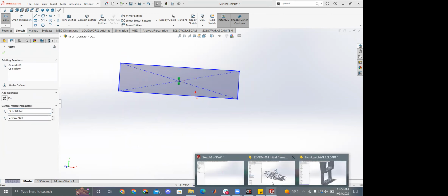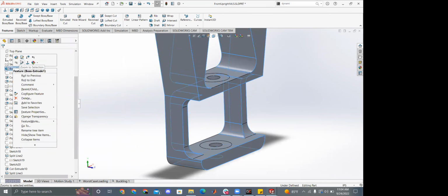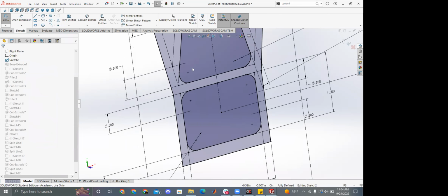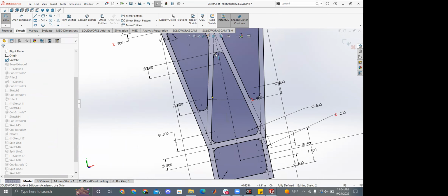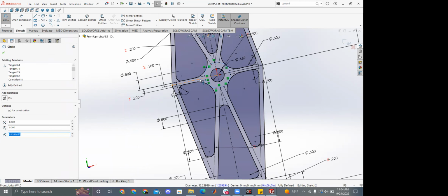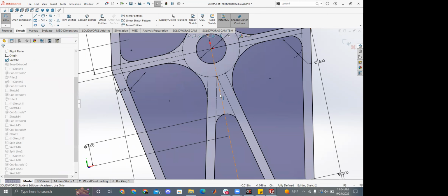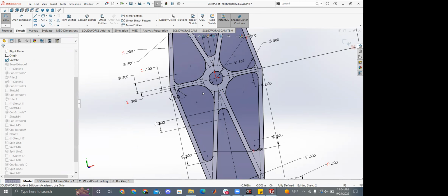Another more impactful example, I suppose, is in this part, which I was surprised was set up well. You can see we have these construction lines pretty much everywhere to show this is the minimum radius I want to support that axle. This is the profile I want my beams to follow. And then you can construct your actual sketch lines around that. It saves you a lot of brain power and a lot of time, and it's a lot easier to edit in the future.